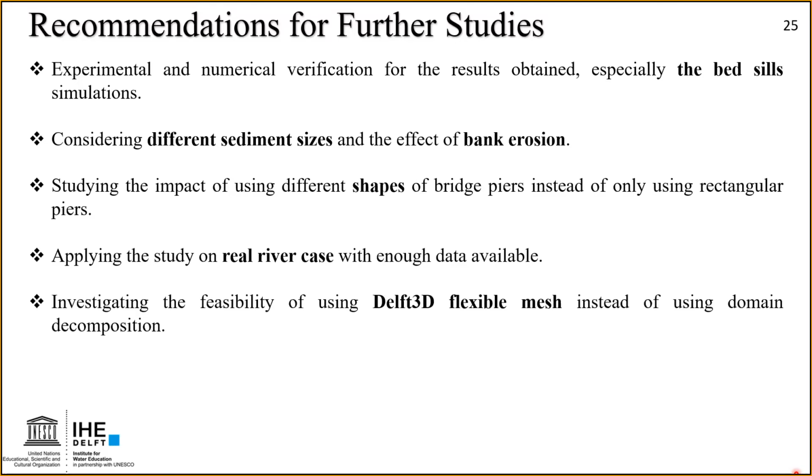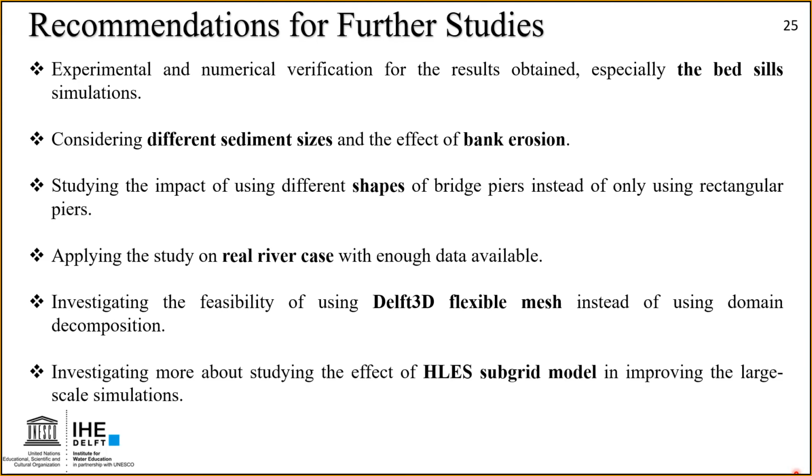I advise investigating the feasibility of using Delft3D Flexible Mesh instead of Delft3D with domain decomposition, because domain decomposition is somewhat complicated. The model also has a lot of limitations and is not very easy to use. Finally, we need more investigation into the effect of the Hillis subgrid model in improving large-scale simulations.